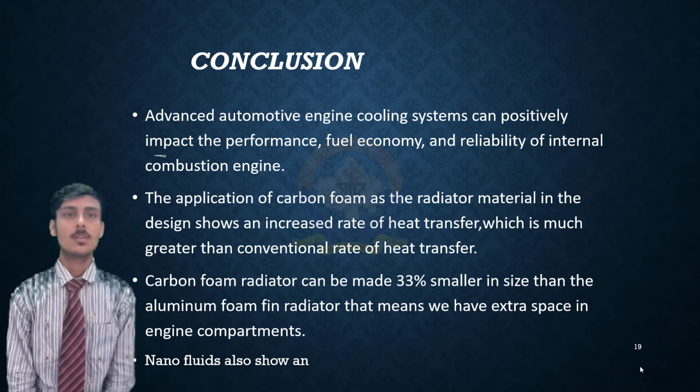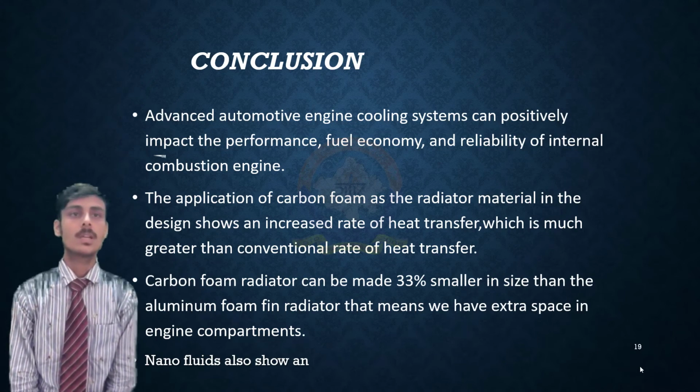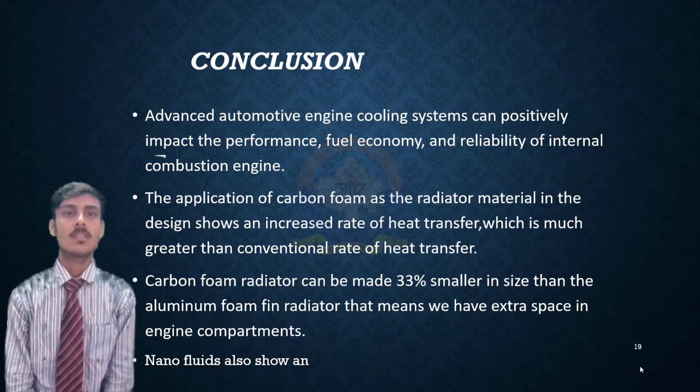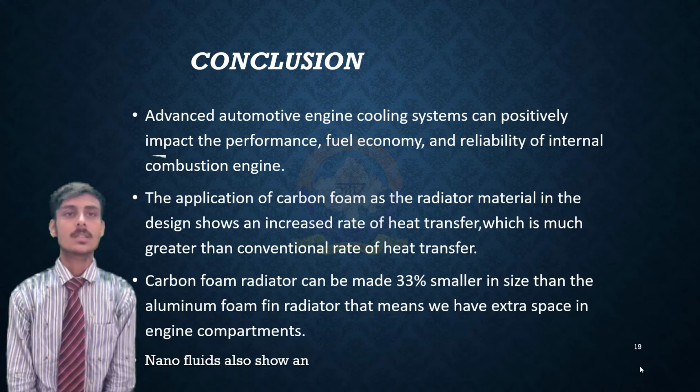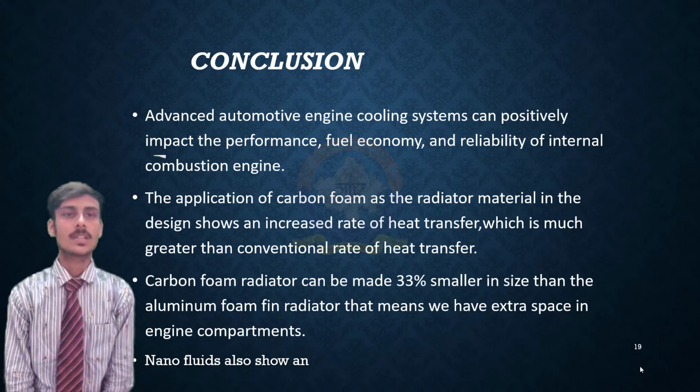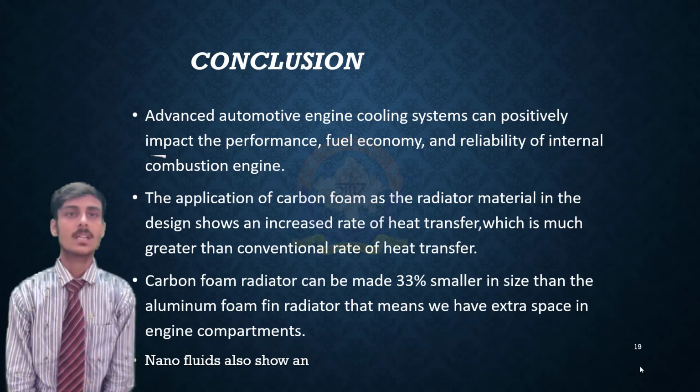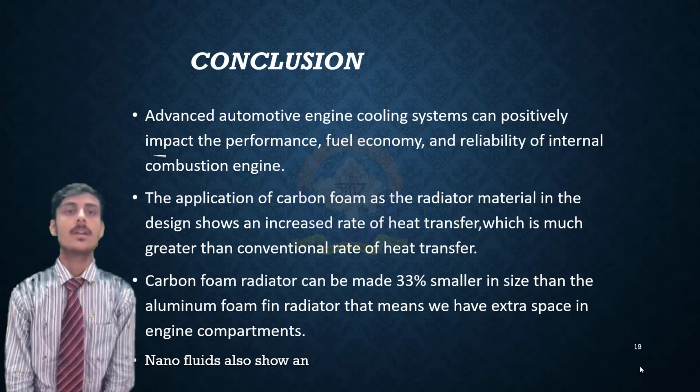An advanced automotive engine cooling system can positively impact the performance, fuel economy and reliability of the internal combustion engine. The application of carbon foam as the radiator material in the design shows that the increased rate of heat transfer is much greater than the conventional rate of heat transfer. A carbon foam radiator can be made 33% smaller in size than the aluminum foam fin radiator. That means we have extra space in the engine compartment.